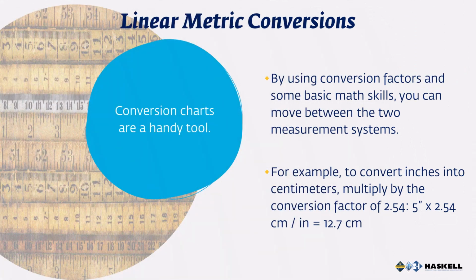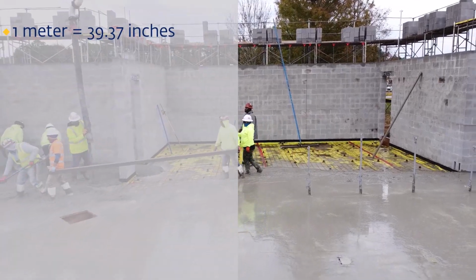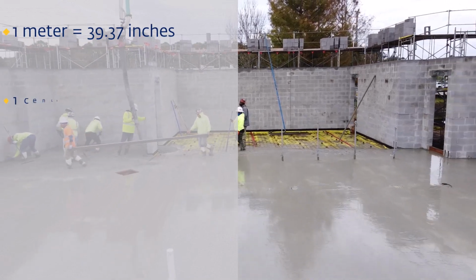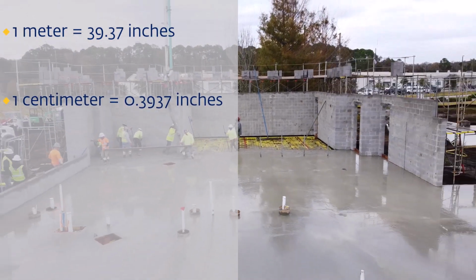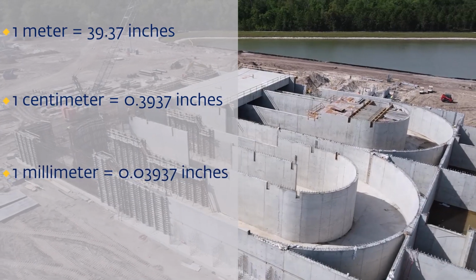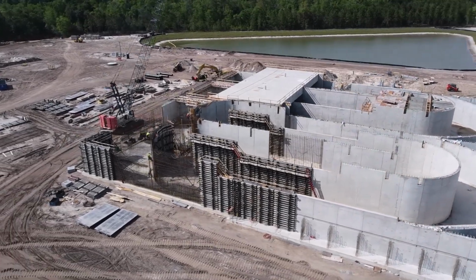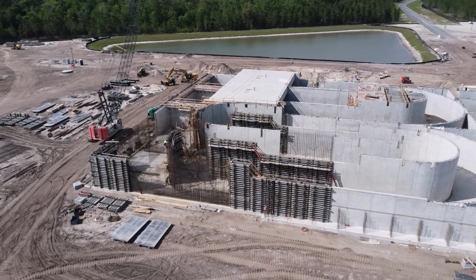Translating measurements from one system to another needs to be handled with great care. Equivalency charts can be put to use to help you convert a measurement from one system to its equivalent in the other. However, you may need to do some math to finish up the conversion. In the English system, 1 meter equals 39.37 inches. 1 centimeter equals 0.3937 inches. And 1 millimeter equals 0.03937 inches.